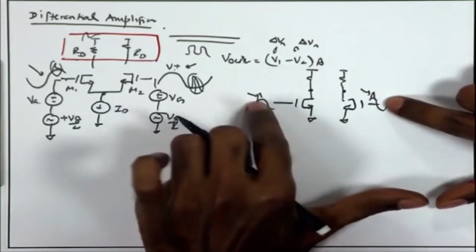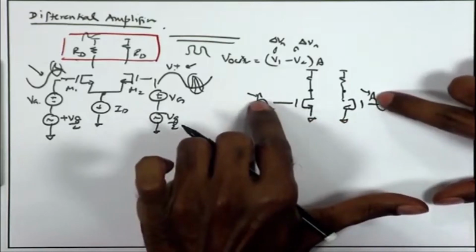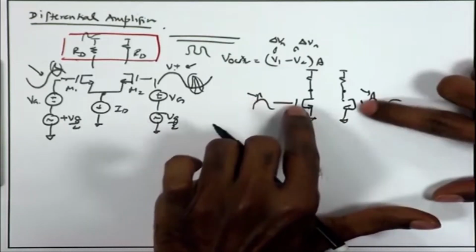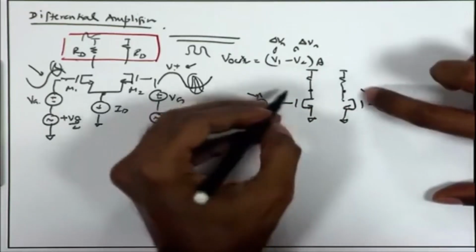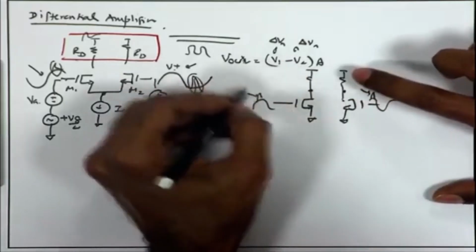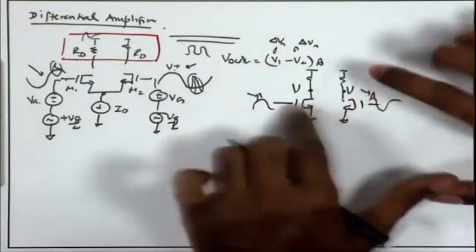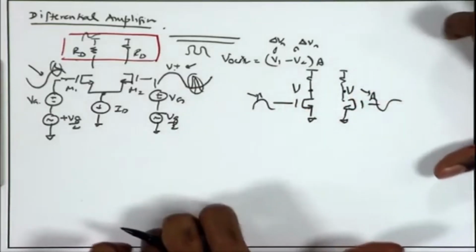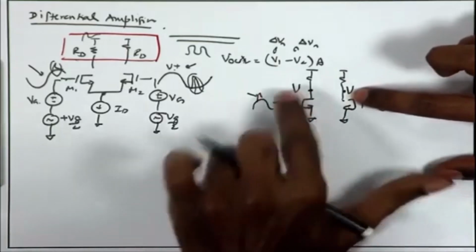Once again, if we do not have this current source, this common signal is definitely going to increase the current in both these branches, and as a result this is going to translate to both the outputs equally, as long as the circuits are well matched. So if I am looking at the single ended output, we are not able to reject the common mode signal.